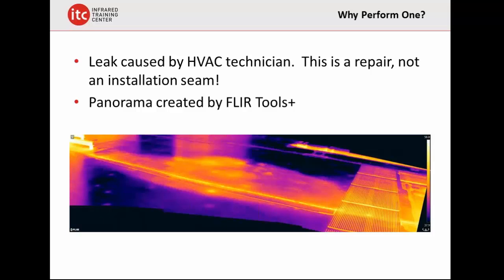It's really not that big a deal from a heat transfer standpoint, and it's a great lesson to take our students to take a look. And on this particular roof for 8 years, we watched moisture move around an air handling unit until they actually removed the whole air handling unit. It's no longer there. And so the moisture can stay in insulation for years and years and years.